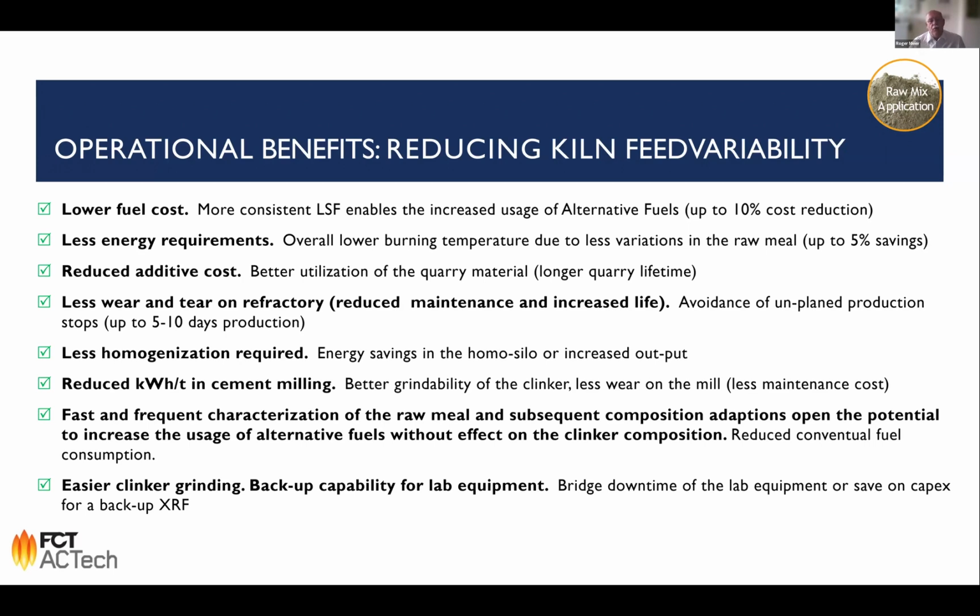At the end of the day, when the material comes out of the kiln, you will see, by having incoming material with very, very low LSF standard deviation, you can produce the clinker on target, which means the clinker must not be overburned, and therefore you can also save energy in the cement milling.